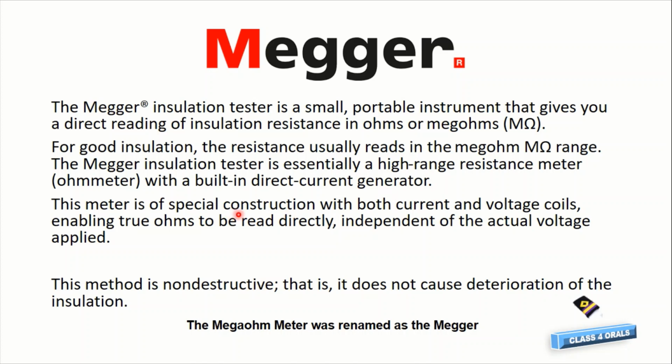This meter is of a special construction with both current and voltage coils, enabling the true ohms to be read directly independent of the actual voltage applied. And this method of DC generation is non-destructive. That means it does not cause deterioration of the insulation. It does not damage. It is safe.